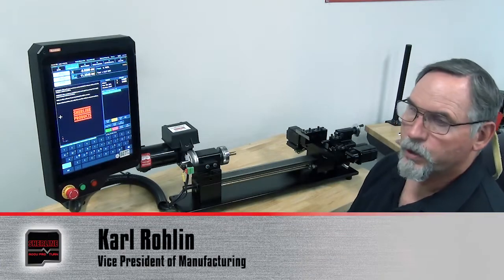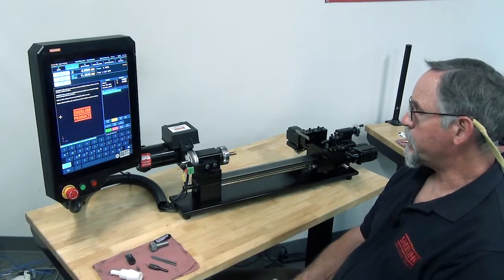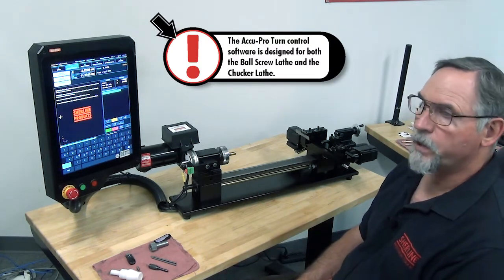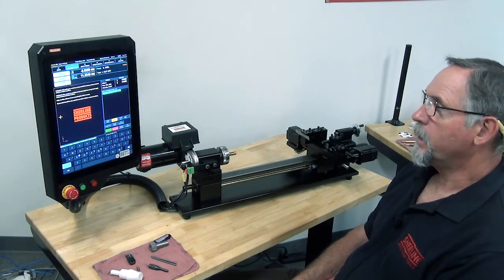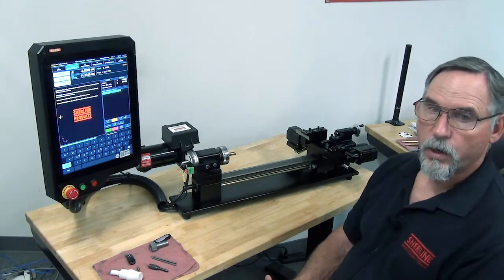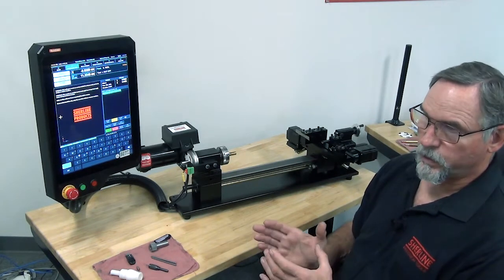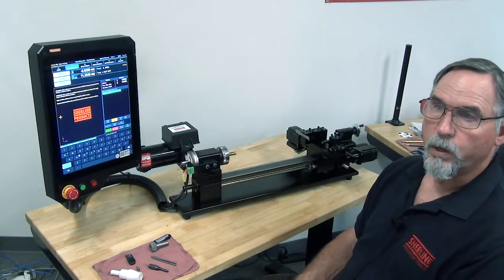In this segment, we're going to go over conversation programming, and because single point threading is one of the things that most people want to be able to do with a CNC lathe, we're going to go over that too. The MASSO software for threading is excellent. I would suggest if you're using a CAD/CAM software to generate your programs, you actually use the conversation program in this to generate the threading sequence, and then just cut and paste that into your main program.